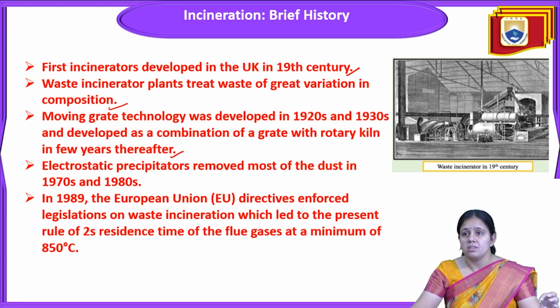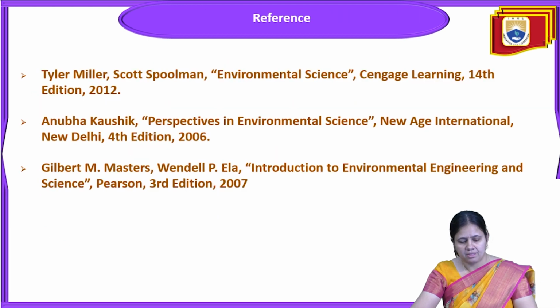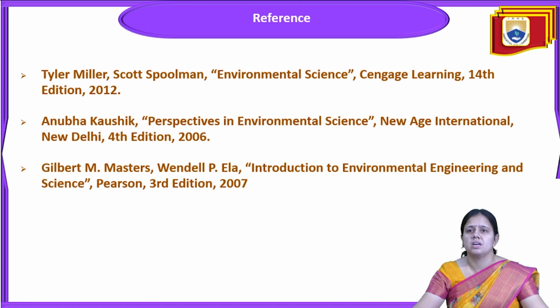So the residence time of the waste inside the incinerator chamber is only 2 seconds, and at a minimum temperature of 850 degrees Celsius. So in 1989, the European Union enforced the legislation on waste incineration that led to the present rule of a 2 second residence time of the flue gases at a minimum of 850 degrees Celsius. These are some of the references from textbooks.